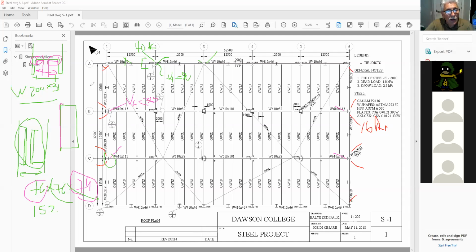beams. Just like this morning, the first thing you do is worry about the number of bolts I need to connect the beam. In other words, you get your VR, and after that you look at the size of angle, and then you go to the other side and determine the size of the weld, and then from the size of the weld you determine the thickness of the angle. And when you're choosing your angles, make sure you don't have a problem, that it all fits inside your column.